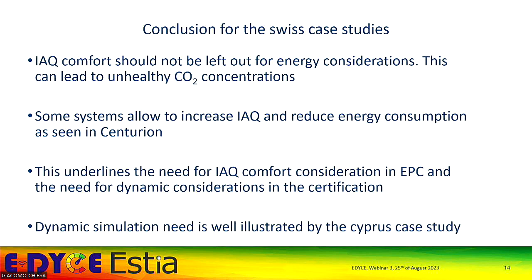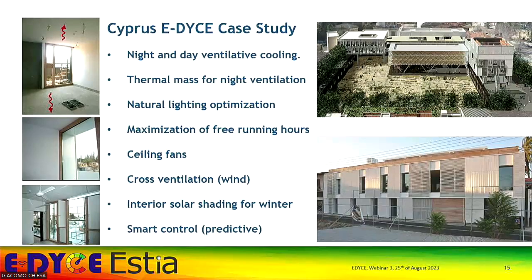And in the Cyprus case studies that I'm sorry I don't have the time to talk about, we have a lot of these dynamic technologies, and they all need this kind of dynamic simulation. So we have night and day ventilative cooling, thermal mass of the building itself, the maximization of the free running hours, the fact that you have ceiling fans instead of ventilation running throughout all of the day. Also, there's quite a lot of wind in Cyprus, so the cross ventilation and the smart control of the building itself.